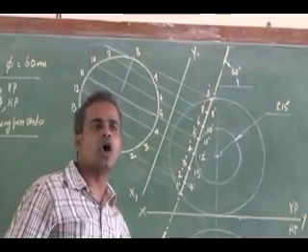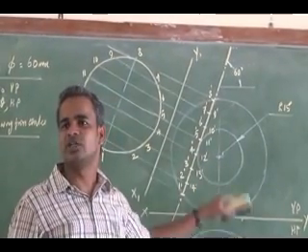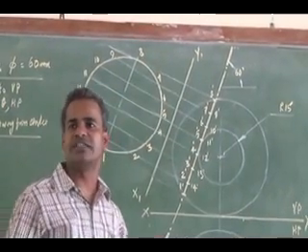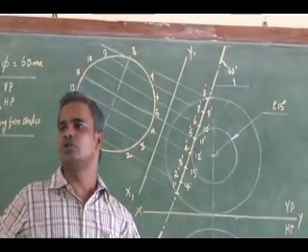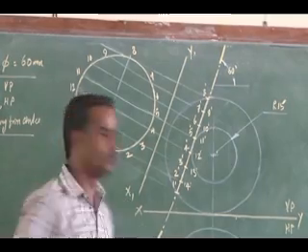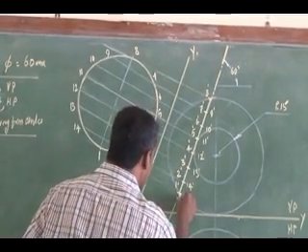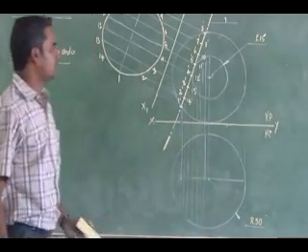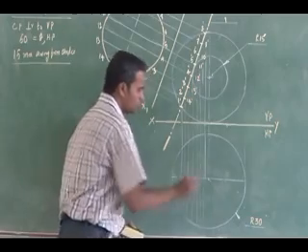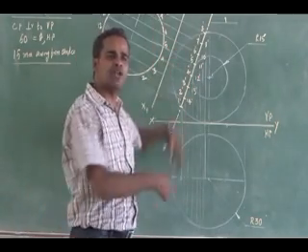Right? Now you have to go for your sectional top view. So how can I proceed for the sectional top view? So these cutting points can be projected downwards to the top view. So the extreme cutting point is 1. Right? Listen. So this is how I have projected the cutting points to the top view.